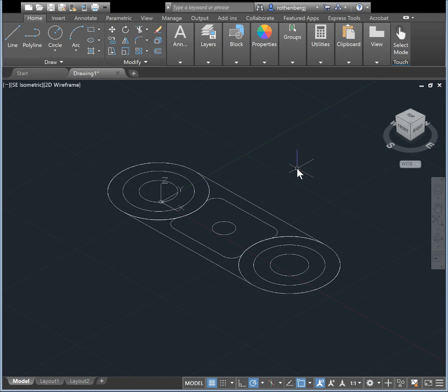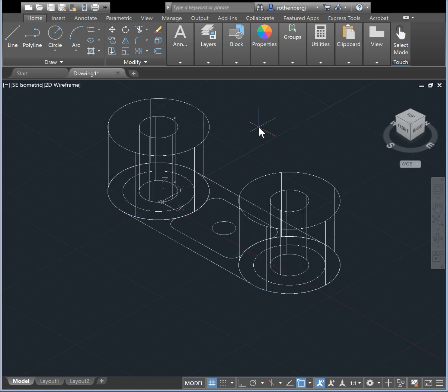So we are going to extrude, and we will select the outer circles. It doesn't really matter how you select them specifically. I personally like to select a bunch of objects in the area using the green little selection area. This will select all lines in its box, and then hold down Shift and deselect the ones that you don't need. So do that for both of the large circles. Make sure you're only selecting those and the innermost two circles of the concentric circles. Now these are going to be extruded up 1.5.